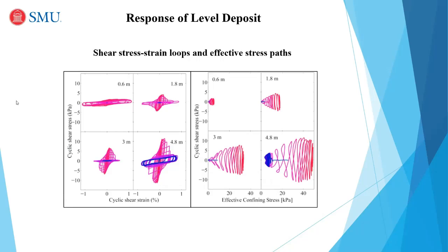Stress strain, we are all aware of what stress strain indicates. So the solid stiffness, basically. The reddish line indicates the early stages of shaking, and then as it gets more blue, it means the later stages. And you can see here how the stiffness degraded as time passes and liquefaction took place.